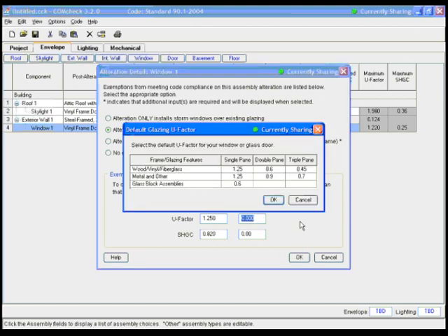And so let's assume that it's double pane. Let's keep it at metal frame. Let's say it was double pane. And you'll see that value is better. They're not favorable. You're still using defaults. But if that's your only case that you can use, if you're just replacing the glass, because it might be that if you're using the U factor for the center glass, that might not get you there. So this is a case where you're going to spend a little bit more time with making sure that you're putting in the right values. And if you are calculating that you're only replacing the glass and you're leaving the framing, that you're putting in the right correction and the right calculation for your U factor and solar heat gain. Typically, alterations, they're replacing the entire frame and glass, but this is in 90.1. This is allowed, and it's just something that you're going to have to make sure you pay attention to.